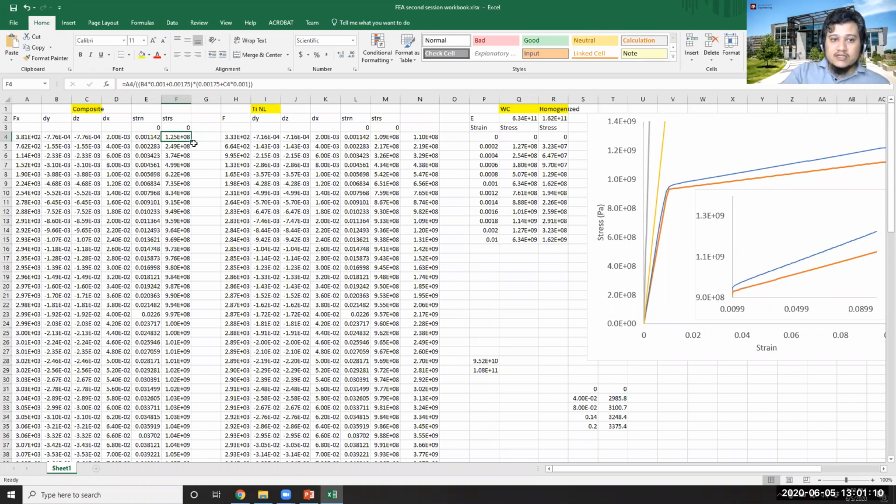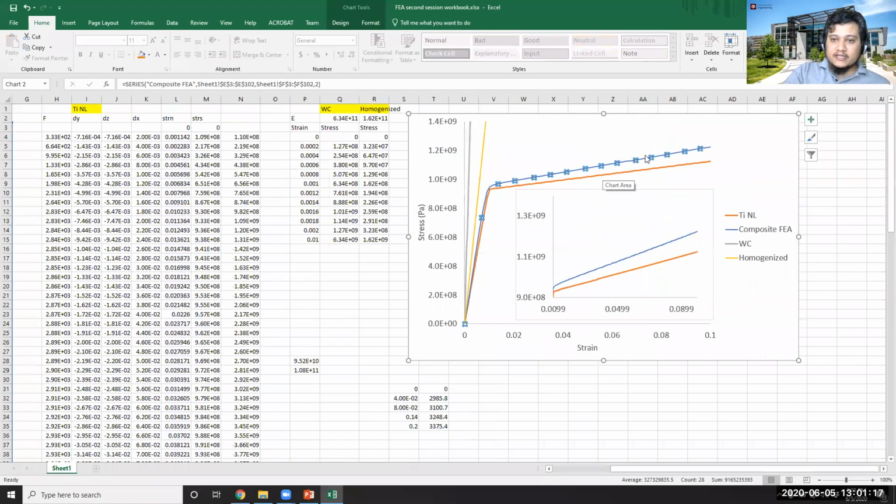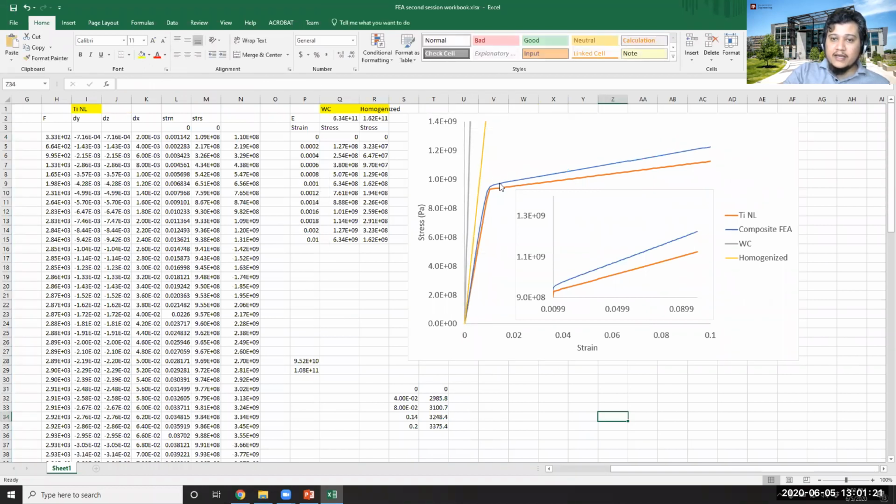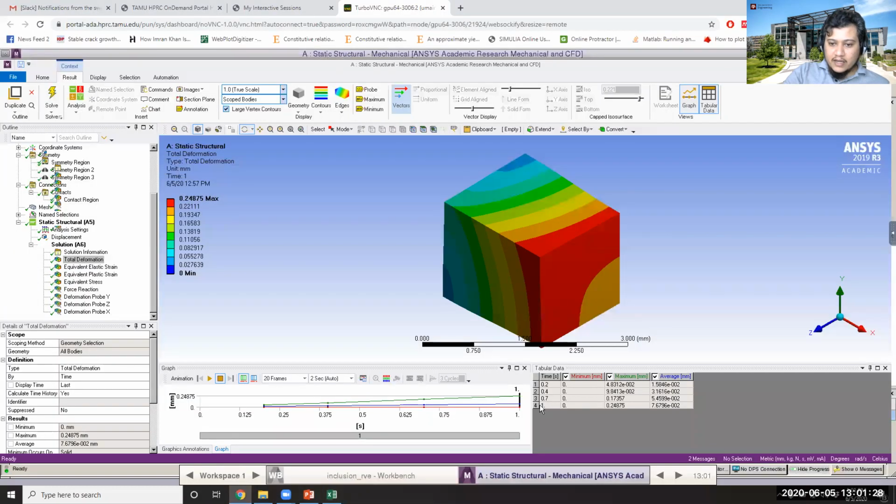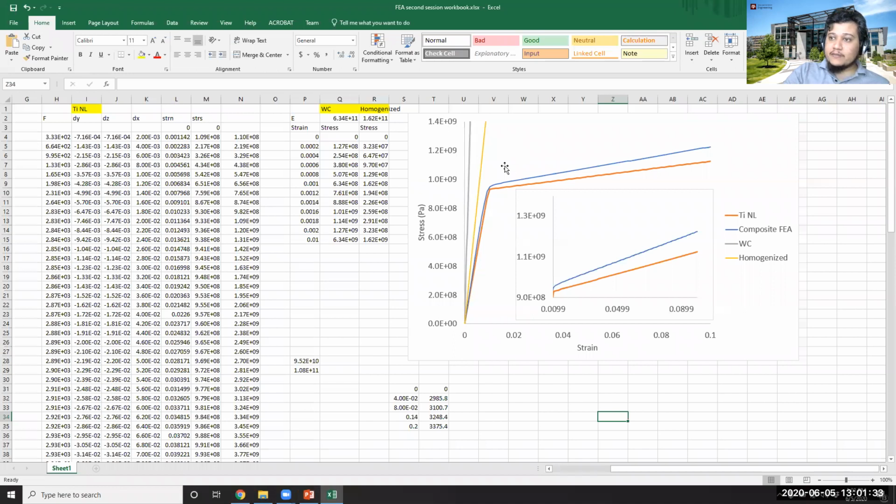Okay, so when I plot this stress and strain response, the result is here. This is the stress strain response, and you can see that I am not having that artifact. The reason being that I explicitly asked for the outputs at more points. Here I only have 4 data points, but I have asked for 100 data points to create this. So this is how I have plotted the result. The blue line is the plotted result of the analysis which we just did.